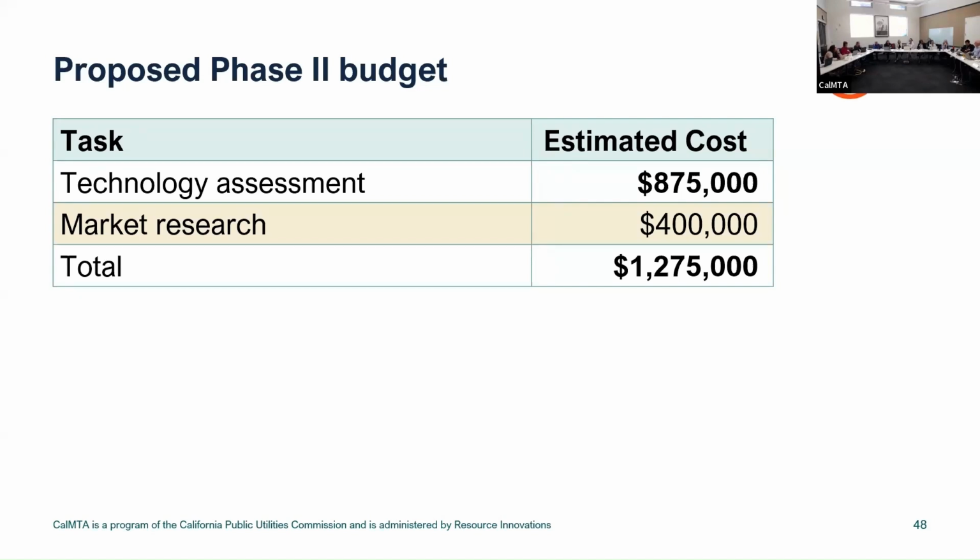Washington, DC, Washington State, maybe it's just Seattle. It's all public information. It's incredibly valuable. It tells you the age of the building, the type of glazing, the type of HVAC, and whether it has been upgraded. You can pretty quickly sort by all of that, and you can also see the EUI and the greenhouse gas intensity, and go, look, of the 5,000 buildings in this region, there's 300 that would really benefit from a combined approach to HVAC and glazing simultaneously.